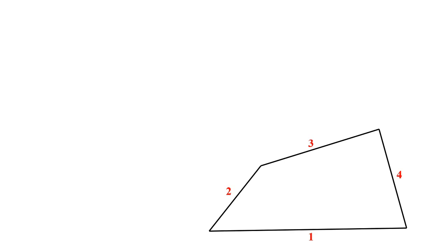Where will I12 be? It is simple. The joint connects 1 and 2. I12. Okay, that is the direct inspection method. Where is I23? Joining 2 and 3. Where is I34? Joining 3 and 4. Where is I14? Joining 1 and 4. So these are our primary centers, and we located them with direct inspection. Clear?